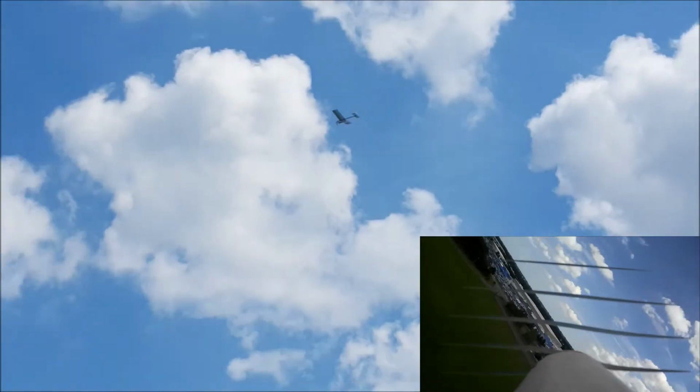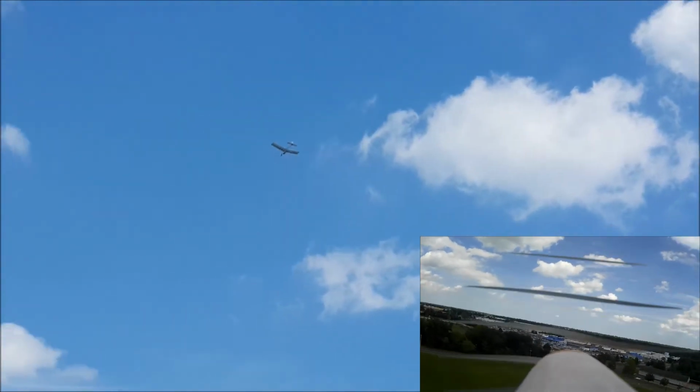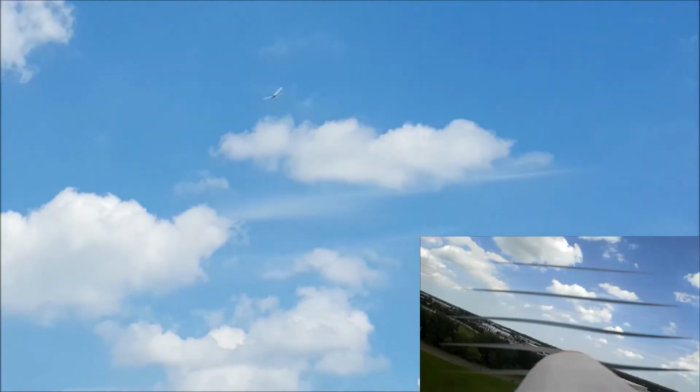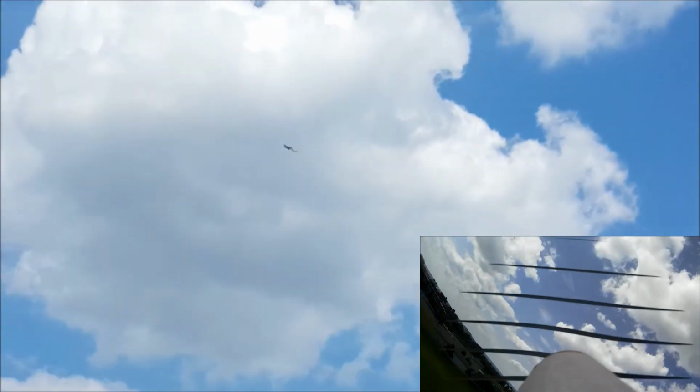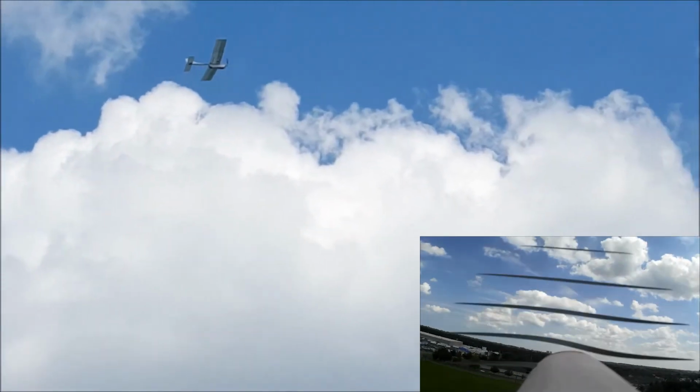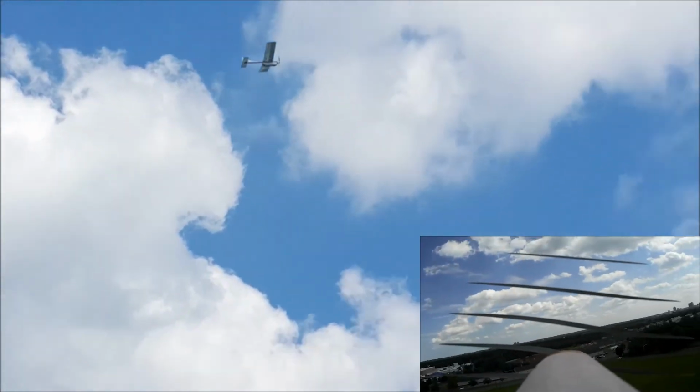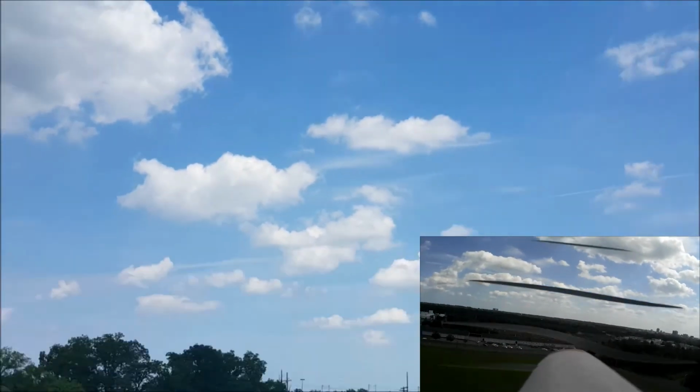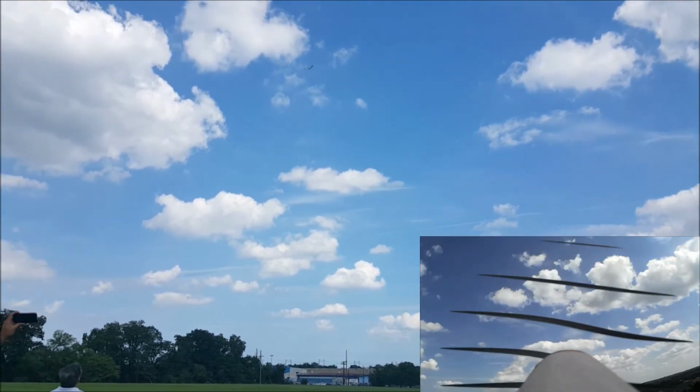At a height of 50 to 70 feet, you can see the plane quickly stabilizes. That's because of the 7-degree angle, which we call a dihedral, and the large wing area. And when the plane's turning, notice how the wings go in opposite directions. That's the roll of the plane. By using the ailerons and elevator to turn, we eliminated the need for a rudder.